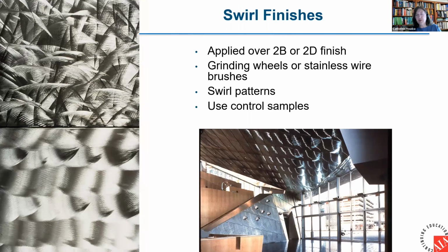The swirl finish is the same exact concept, but in more of a pattern. This is generally applied using a computer-controlled setup to create a consistent pattern, although it could be done by hand. These last two finishes are quite rough, so you generally would not want to use them outside. Otherwise, you might have a corrosion issue that wouldn't otherwise happen with a smoother finish.